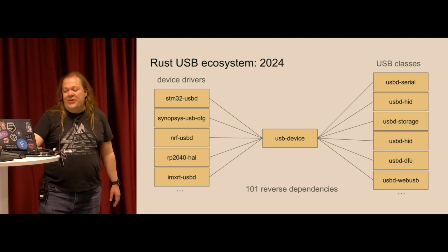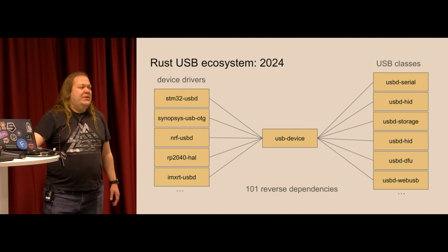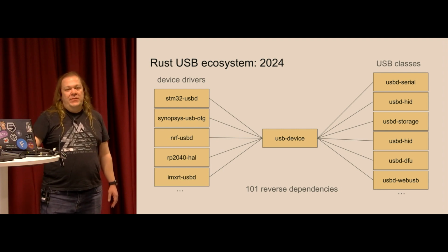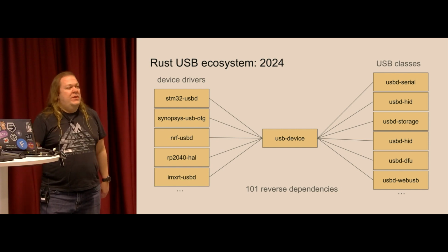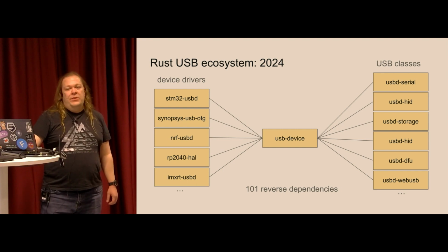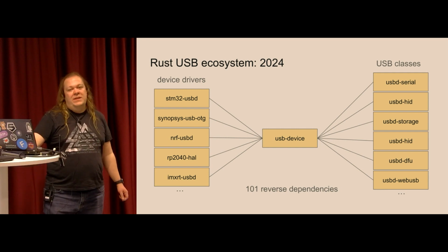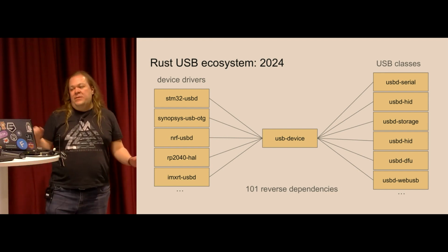We even have a WebUSB class, which implements a really interesting concept where you can control your USB device from the browser. Modern browsers, well, I don't know, maybe even Firefox nowadays supports this, but this is really convenient sometimes when you want to simplify life for your user. You can just implement some website and then connect this website to your device. Implement automatic firmware update, whatever you need.